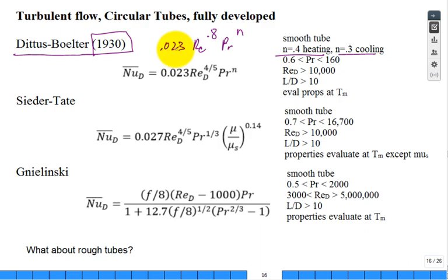So, all right. You can see this one is out. Again, if it's applicable, these are the range of the Prandtl numbers, 0.6 to 160. That covers air and that covers water. So you're good for a lot of fluids.